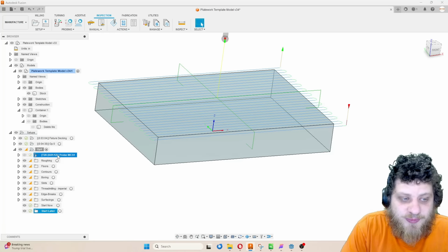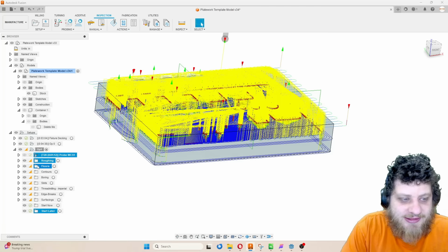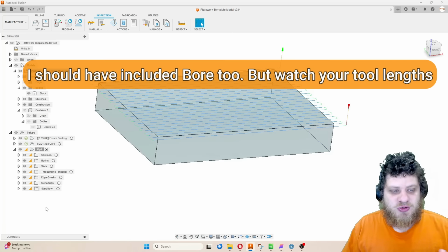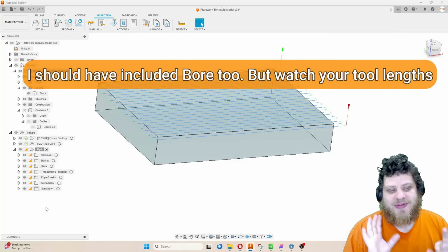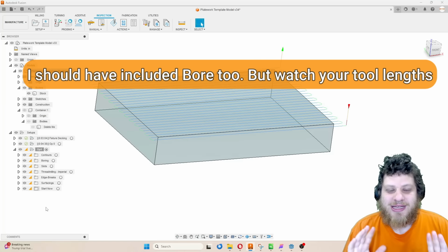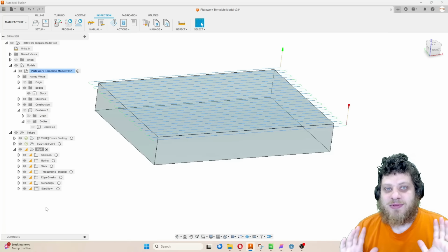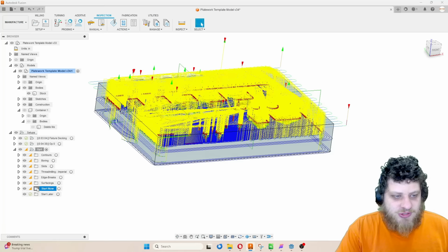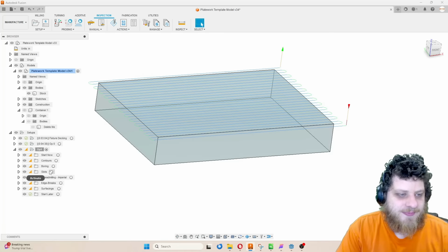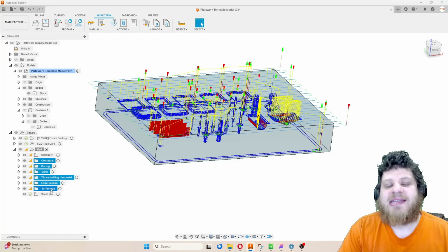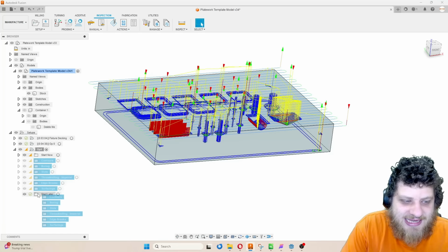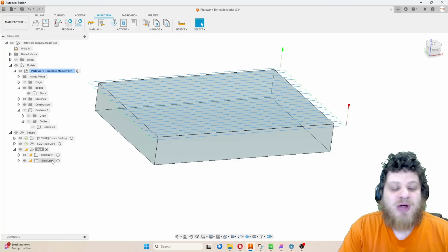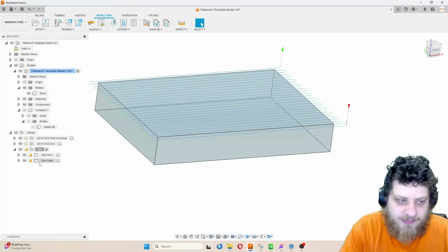Now, some of these tool paths, like the probing, the roughing, and the flat tool paths, those tend to be very safe. You can do just a quick simulation, and if that simulation's good, you can hit go before everything else is programmed. So I'm going to move that folder up to the top here. These other tool paths, they need a little bit more babysitting. They take a little bit more time. And so I'm going to put those in the Start Later folder.